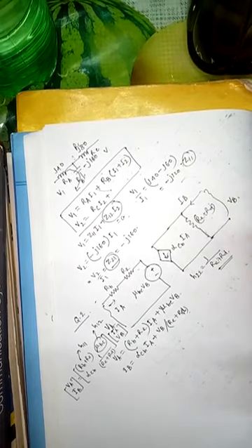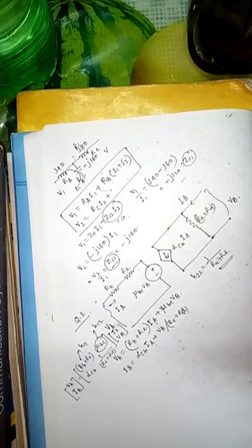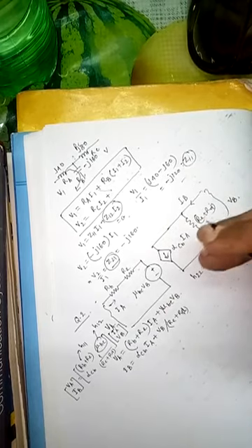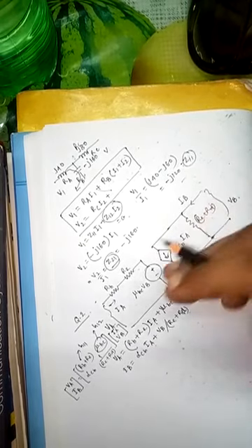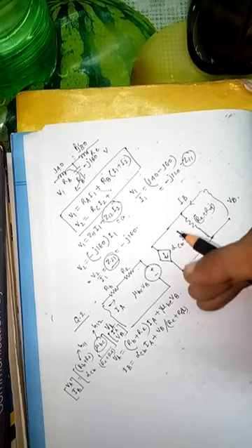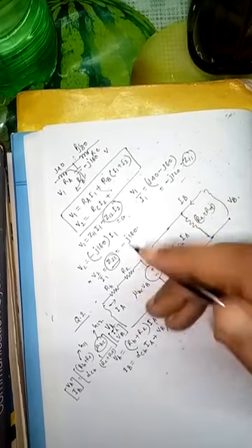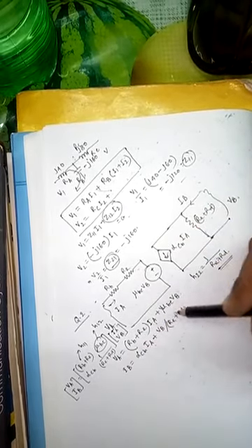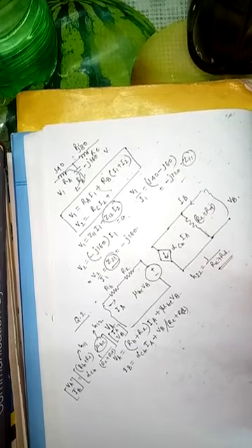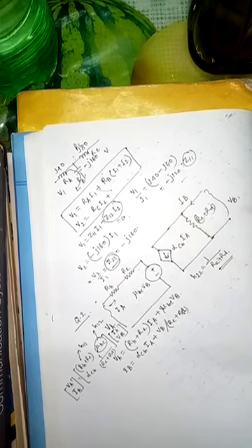Just consider what is being asked in the paper. Suppose it asks you to find the Z parameters. If using the H parameter is easier, find the H coefficients first, then convert from H to Z. You can easily find the Z equivalent matrix and the Y equivalent matrix.